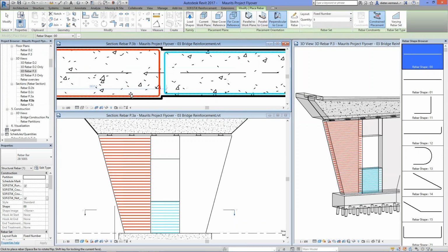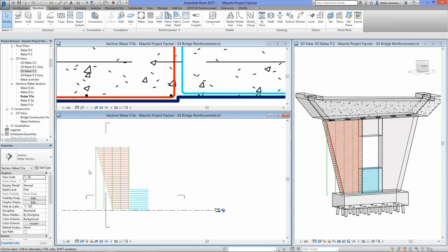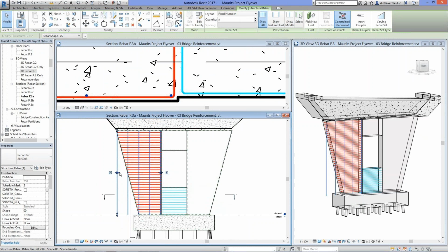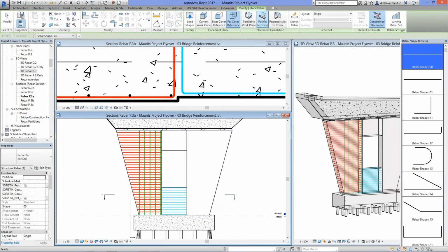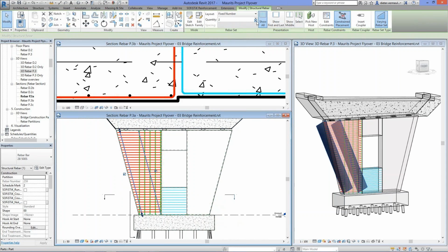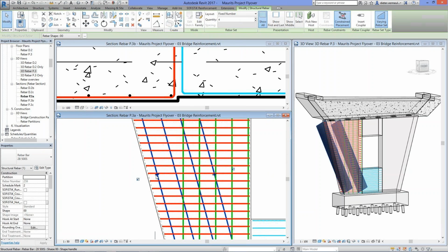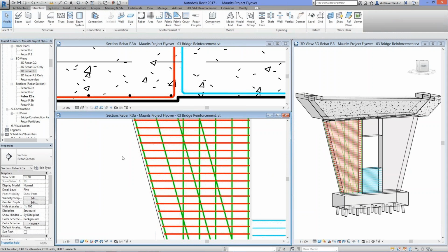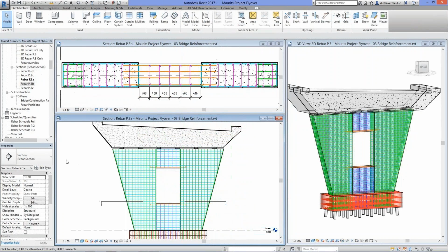And also remember, this is not only a drawing, it's a model. And these rebars can have parameters like, for example, weight, so that you know later on how much weight is needed or will be placed to some piers, etc. So you see that you can specify how these rebars will be placed, parallel, perpendicular, and the system knows about the constraints, about the shape constraints, and you see just really simple shifting, having some parameters.